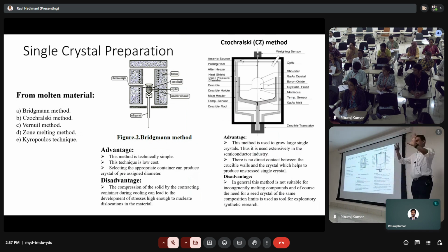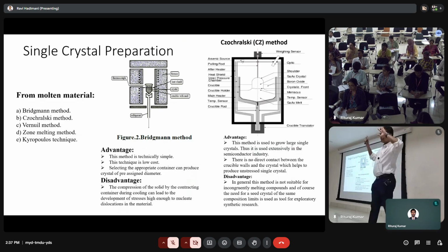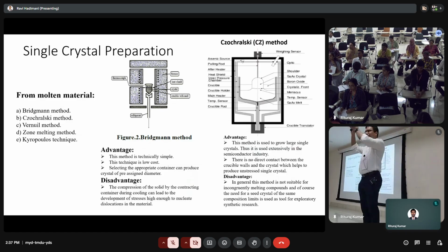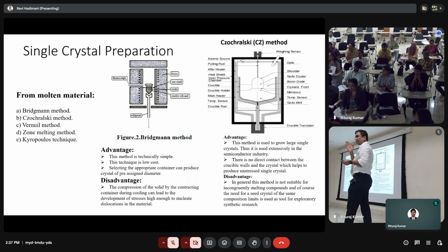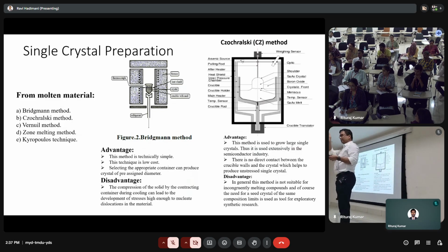Yes, the name suggests: one crystal all aligned, versus polycrystalline, smaller crystals misaligned. But how does it translate to properties? That's correct. So in single crystal, you get anisotropic properties. That is, along one axis you have different properties, and along another axis you have different properties.